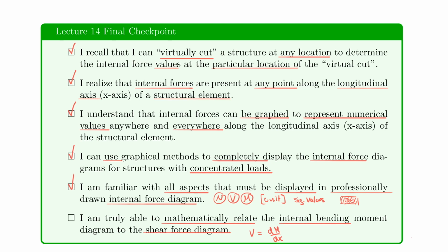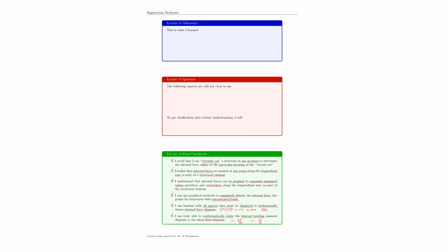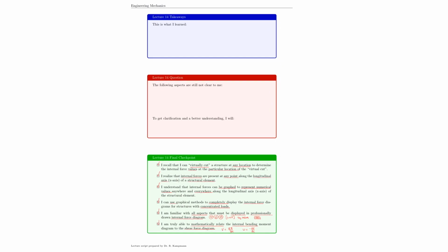Likewise, we also learned that the load case, which we call w, is equal to the negative of dV/dx. We actually had the negative on the other side, but you find it in different textbooks one way or the other, either minus here or the minus here. It means the same thing. However, I hope we truly understand this after this lecture. At least I could visually convince you of that, and you can convince you further through the following homework. But this definitely summarizes our lecture, and we are now happy to study the homework and can take a look at the upcoming problems on the next page.